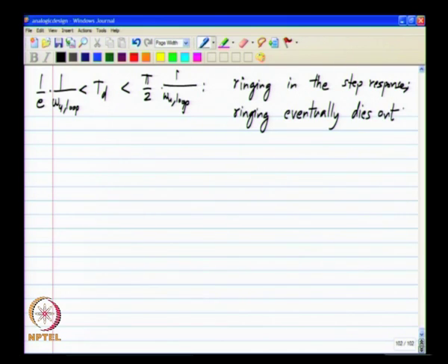Okay. So, the system is stable in that if you apply a step there will be some ringing and that thing eventually dies out, and the same thing is true if you have initial conditions in the system, they will eventually die out, but there can be a lot of ringing. You can tolerate a little bit of ringing, but usually not a lot of ringing.